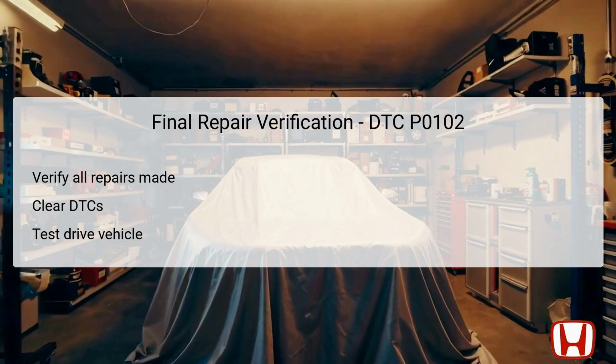After completing all necessary repairs related to DTC P0102, it is important to verify that all repairs made were effective. Begin by clearing the DTCs using the HDS to reset the system. After this, conduct a test drive to monitor the vehicle's performance and check for any return of the DTC.